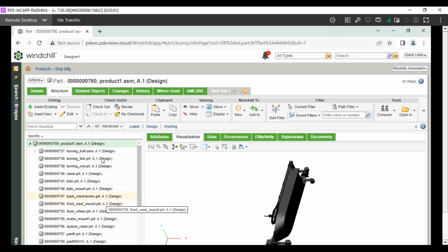Before that, we need to make sure that this particular eBOM has all its manufacturing related information present with it, such as whether it has its exact raw materials, and whether it has related process steps allocated to it. So all the planning is done using Windchill MPMLink. To start with, let me show you how we differentiate between an eBOM and an mBOM first.